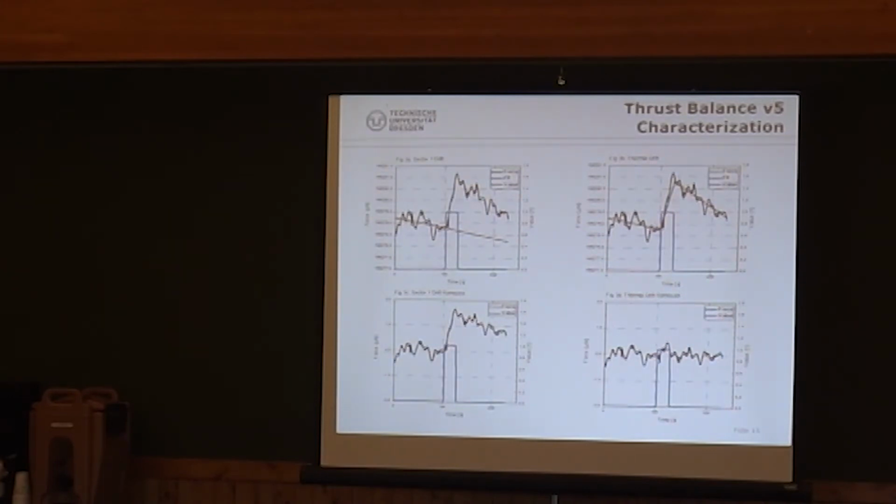If you apply a current to your thruster, it will heat up. And I mean, the Woodward Thruster, we put 100 watts into it, and it's very huge power, it will heat up. By the way, the thrust should respond similar to this. So it should go up, keep a straight line, and then go down again. If you have thermal drift, it will look more like a straight line. You will see how thermal drifts actually look like in Marcel's presentation later. But that's how we do it.